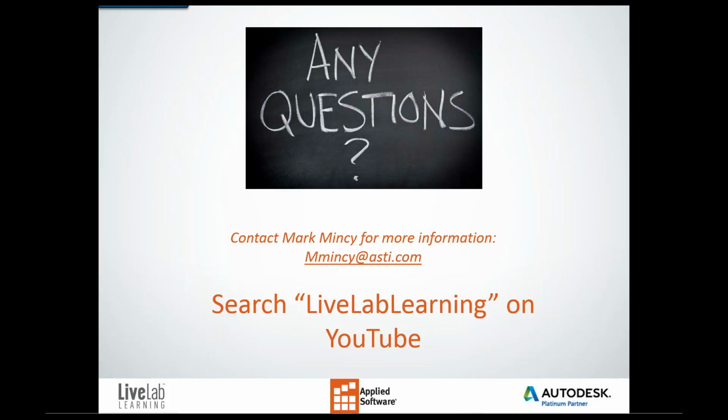Now, when we each open up a project, we're making our changes. We synchronize our changes back to what's called the central file. Let's say, Jillian, you're adding some information to it. When you synchronize it, it just sends that delta change information back to the central file. And then when Mark and I synchronize, we get that information to our drawings.